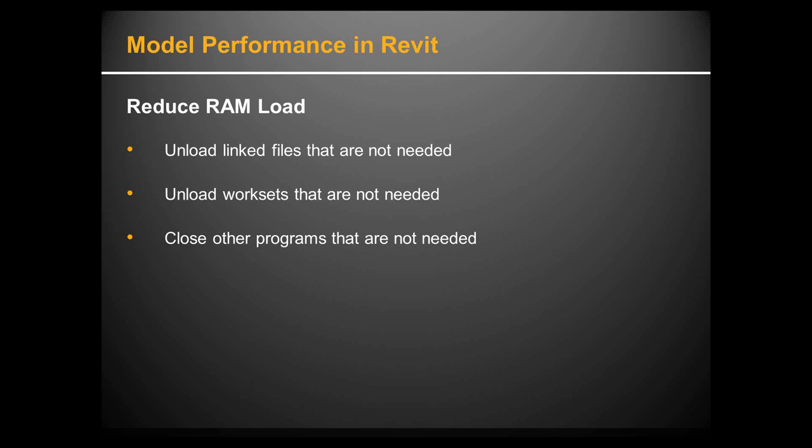I think you can use worksets in a single environment and use them to unload big things that you're working on. So even a single-man firm can be using worksets to turn off parts that they're not using within the model. There's not a problem with that. It seems to work just fine, and it's going to speed things up. So getting used to using those worksets, if you don't know what they are, we can definitely walk through that at a later date, because I don't think we have that today specifically. No. But using worksets, it's like AutoCAD layers on steroids and energy drinks. So that's a great place to start with it.